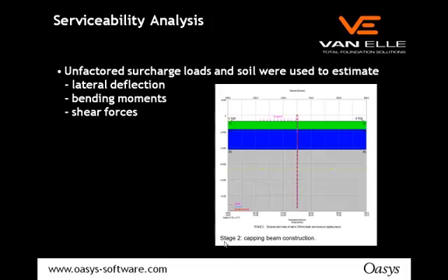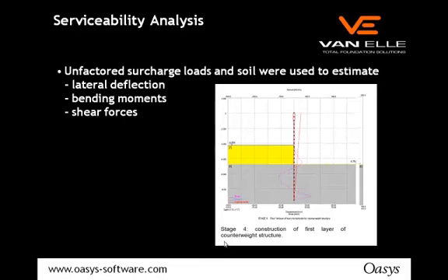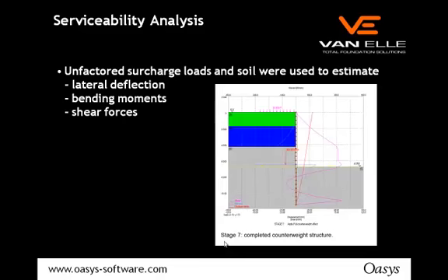So if we go through the construction sequence here, you can see they're showing the capping beam construction. It goes on to show the simultaneous excavation of both sides of the wall to formation level. And then it analyzes the construction of the counterweight structure. So here's the first layer of the counterweight structure and the completed counterweight structure with loading here, showing here for